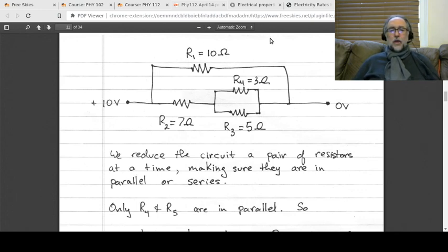So you take a look at the circuit and you say, are there any that are purely in either series or parallel? And you say, well, is R1 and R2, are they in parallel? Not quite, because there's these guys in the middle. Okay, so those guys are kind of messing it up. And you can say, well, is R2 and R3, are they in series? And no, because there's a split in there, and that's kind of messing them up.